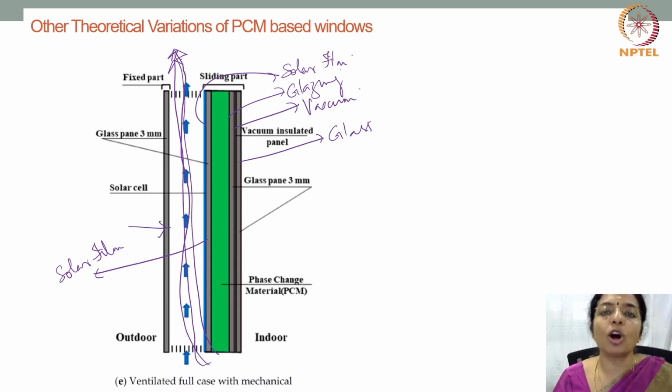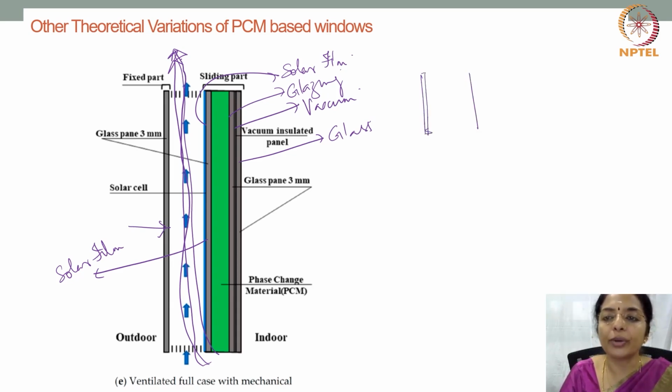Because of the small thermal mass and physical properties, they are considered a barrier for heat loss and heat gain, depending upon what all layers you add, whether it is just two glass with phase change material, or you can have a single glass pane in section, or a glass pane with a PCM, or a glass pane with a solar PV film and PCM, or you can have